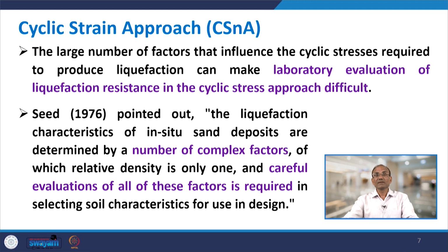As a result, in 1976 it was pointed out that liquefaction characteristics of in situ sand deposits are determined by a number of complex factors. Out of these, one of the most important and normally used is the relative density of the soil, but that is only one factor, not the sole factor. The relative density of the soil and the void ratio are more or less the same thing. On another side, it is sometimes represented using SPT N values.